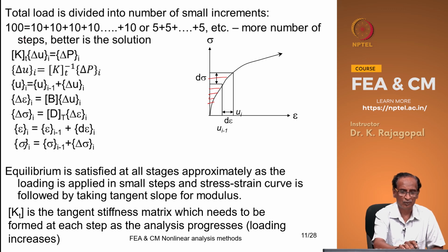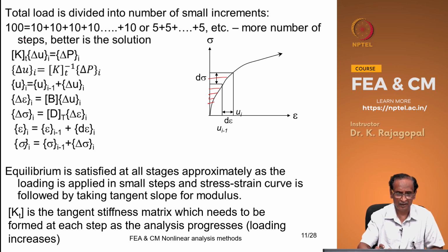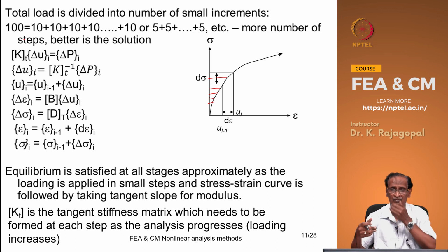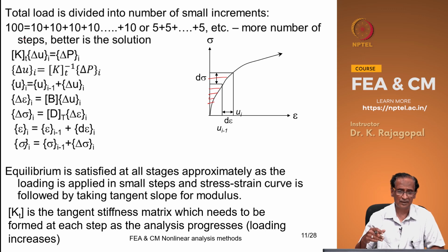Let us say you want to apply a pressure of 100, you can split that into 10 kPa each and apply this 10 times, or 5 kPa and apply it 20 times, and so on. And the more number of steps that you use, the better is the solution.